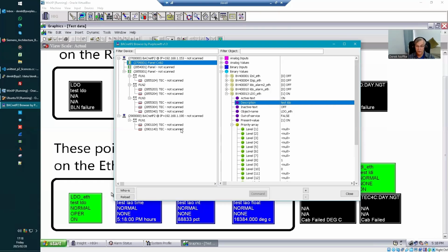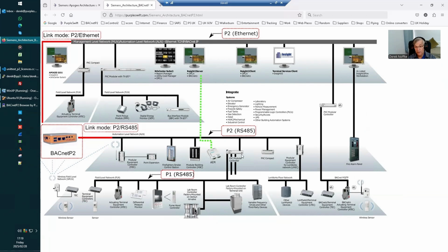Most contractors who go into a site want to integrate the site to the new system, but then they want a plan for how to upgrade the system so that when a device fails, how do they replace the parts without breaking the system? These devices have got these PPCL programs in, and they can depend on each other, and that's the catch. And we have tools in place to let you know exactly how to handle that.